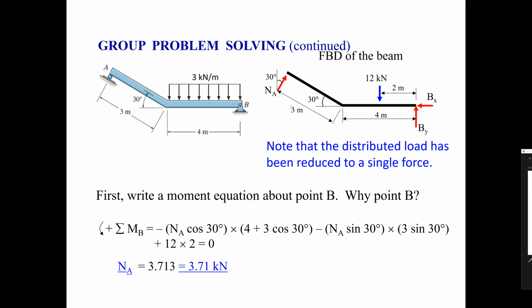And then we can use that, along with the y component of this thing acting straight up, to come up with the moment due to the y component. Okay, so the part that's acting straight up is the cosine of this. Here we have NA times the cosine of it. That gives us the vertical component of this force. And then here, 4 meters plus this, which is the length from here to here. So this gives you the moment due to the y component of this reaction.